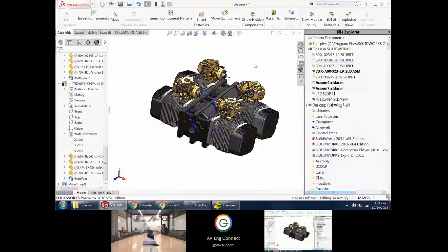If you pick a combination, like 3 faces, you have to have matching 3 faces on the other side. You can actually name each mate reference, and you can have a similar mate reference on another component if they find each other. Like a USB is a really good one to do that for. Where if the USB plug has the 3 mates it needs, and the USB receptor has the 3 mates, they'll just snap right into each other. When they say, oh, you got a USB mate, I've got a USB mate, let's put them together. So it's a little bit harder to keep track of if it's trying to look for the matching geometry or if it's trying to match the name somehow.